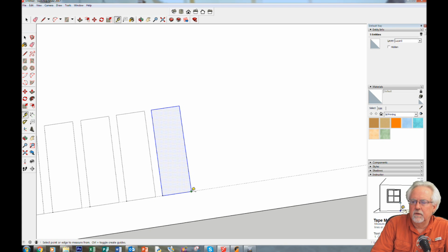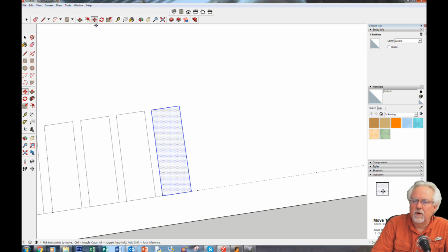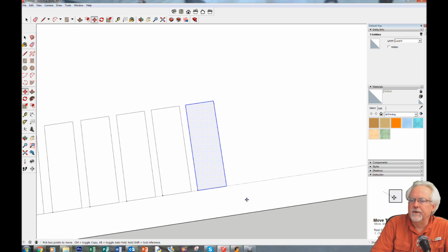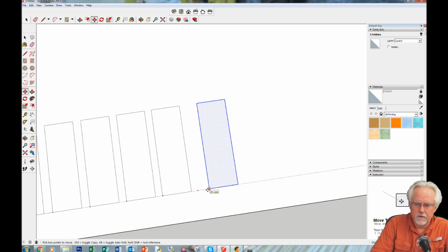We're going to be at 1.1. Okay, grab the move tool, grab the corner, tap Control. That's our 1.1. Okay, we are going to go to 1. We're about halfway through with this thing. Type in 1, enter, move tool, grab the corner, Control.